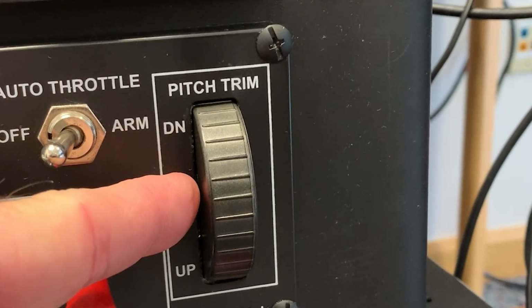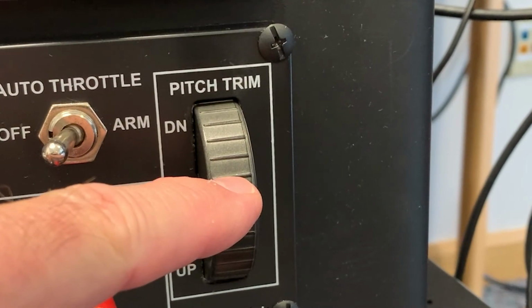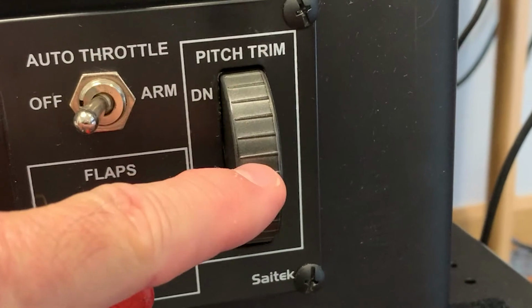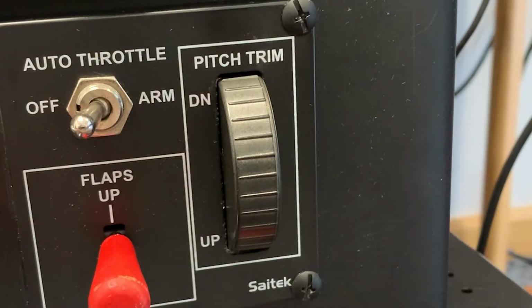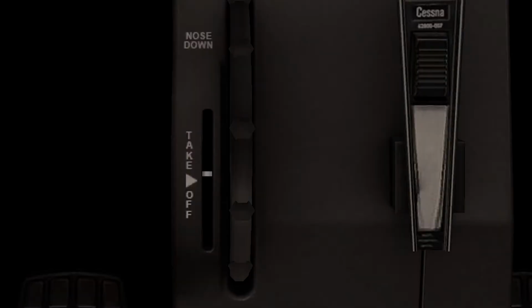Controlling the trim tab is done by rolling the trim wheel forward for nose down trim or backward for a nose up trim. I'll explain how this affects your speed in another lesson. For now, just know that if your plane tends to go nose up or nose down without you moving the yoke, your trim is probably not set correctly. For level flight, it should be in this area.